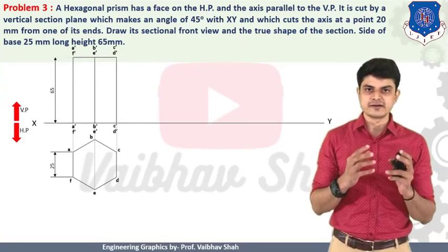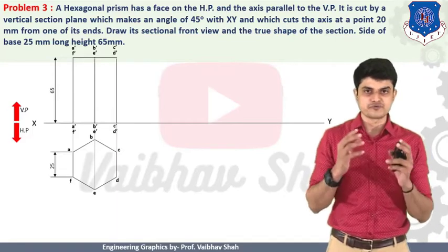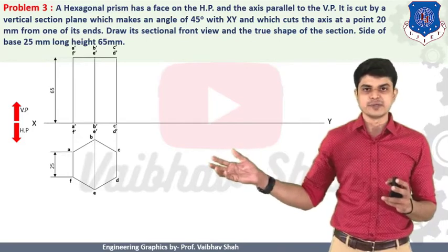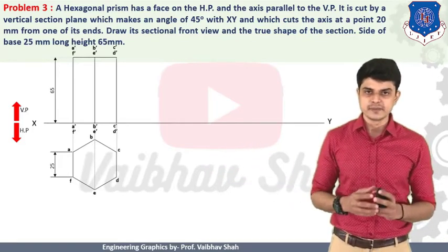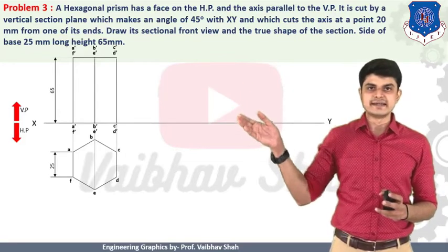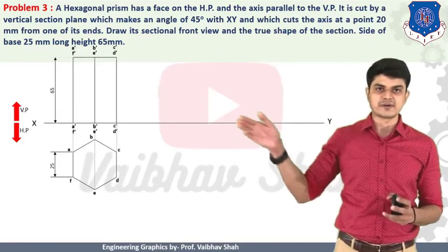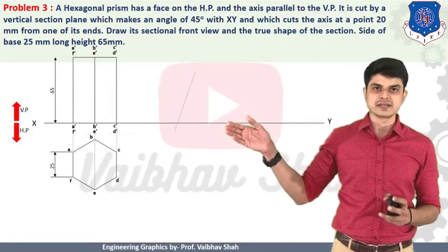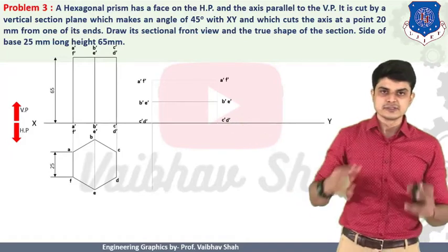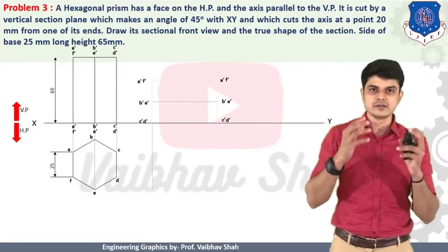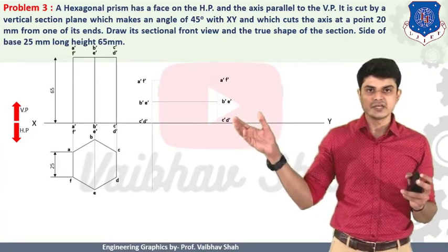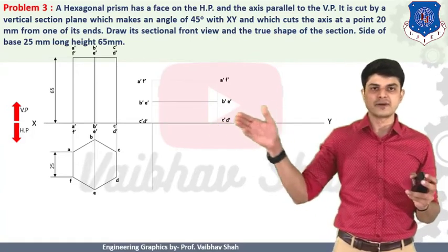And if you need to represent your rectangular face in your front view, you should obviously draw a hexagon in such a way that you should have this vertical line on the right hand side. So now let us put this vertical line of C dash C dash and D dash D dash onto this horizontal XY line. So let us put this object like this. We will be having our final object something like this. So this is nothing but your hexagonal prism front view drawn in the same position in which your rectangular face is now on your XY line.